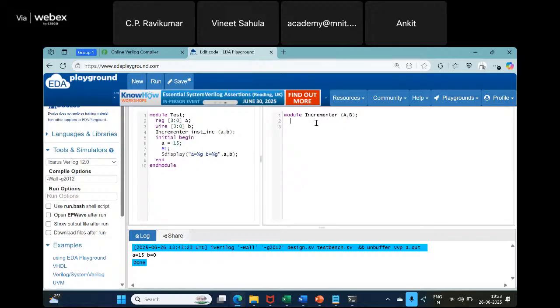So I will have to create another module called half adder, which takes as input 2 bits. Let us say we call them in A and in B, and generate sum and carry. Okay? And you may know this. Sum is nothing but, anybody remembers the sum expression? It is nothing but the XOR of in A and in B.